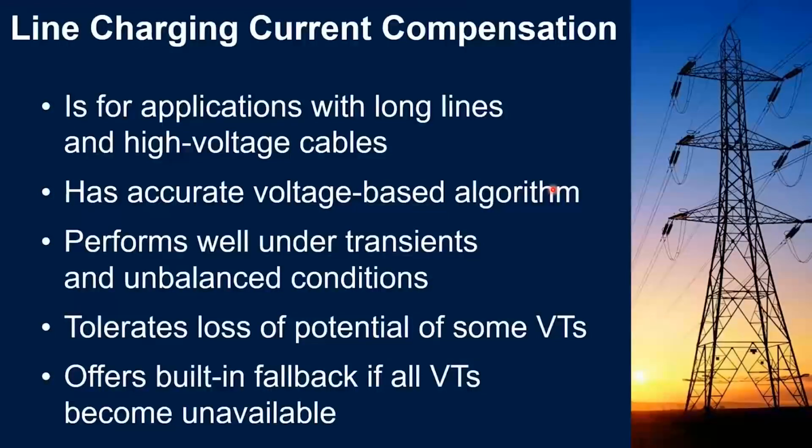This is a differential current by definition, and when lines get long, this can start to be a significant number of current. So to handle this, traditionally, you can increase the operation threshold of the differential protection, but you will also lose sensitivity by doing this. So what we do is a voltage-based algorithm, which will perform well under transient and unbalanced conditions.